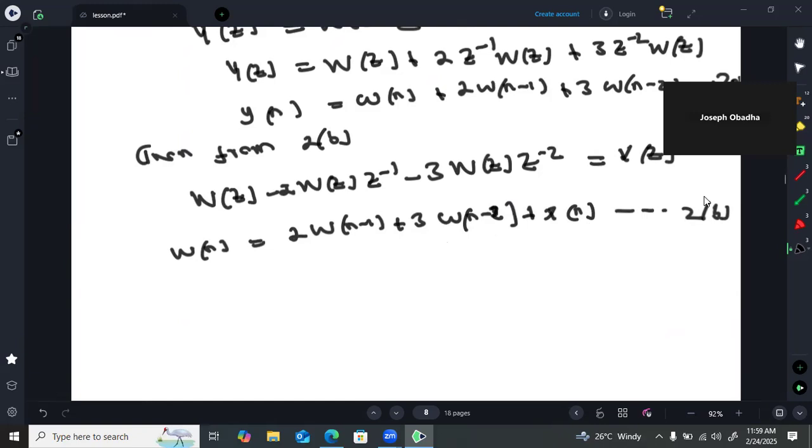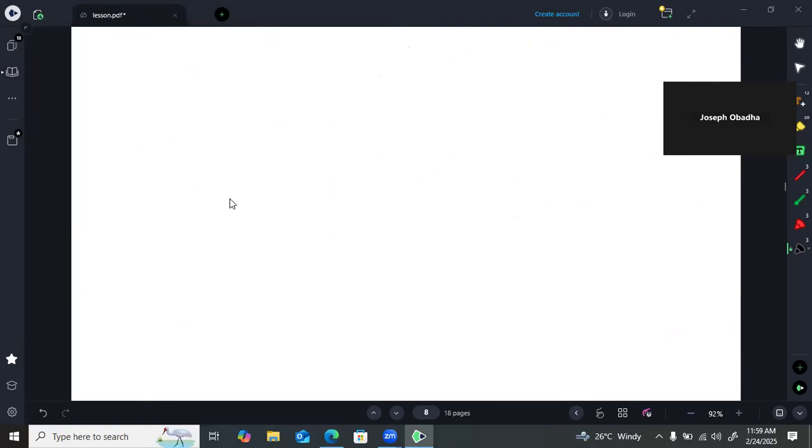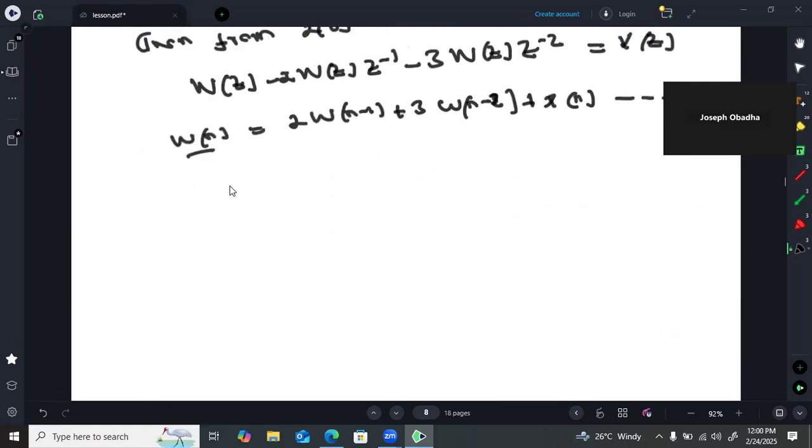So we sort of come very close to the direct form 1 at this stage, because the implementation would remain the same. I will implement the part where the x is the input, then w of n still appears as the intermediate variable. So if I do that, we start by implementing equation 2b.